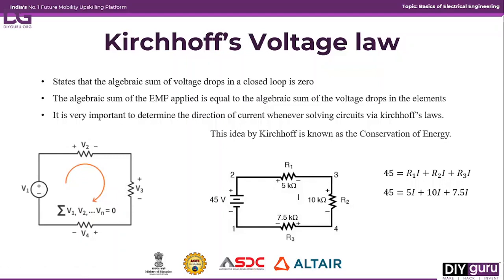Okay. So here we need to remember one point: while applying the KVL, the direction of the current plays a very important role. So first we need to determine the direction of the current. We need to allot a current direction. In this direction only we need to apply the KVL.